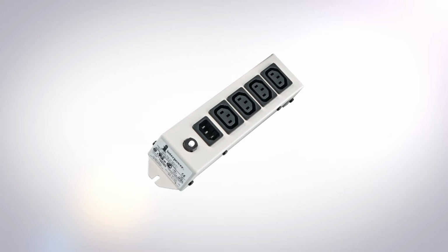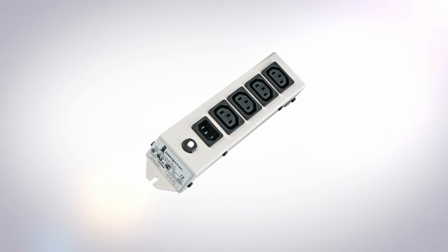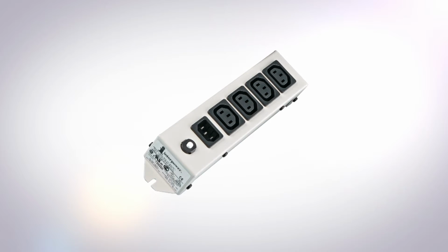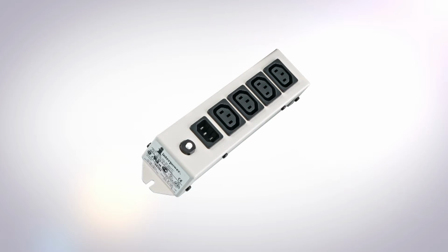And I guess the final component in this accessory power system is the accessory power strip, or the APS. Why is that such a key component? At its core, the power strip incorporates all the AC power components needed in this accessory power system. It'll typically have the inlet for the power coming in, and will have typically 4 but as many as 20 outlets to spread the power out to the peripheral devices.